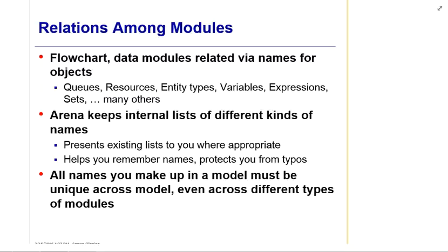Same way as if you set up a record, if using a record module, if you set up a variable of something that you want to look at, whatever it might be, you can access that and make decisions on it as well. So if there's some unique things to your process that aren't captured with the standard set of characteristics that Arena captures and keeps in a database, you can establish your own and then utilize those, again, further in the process or further in your simulation to make decisions on.